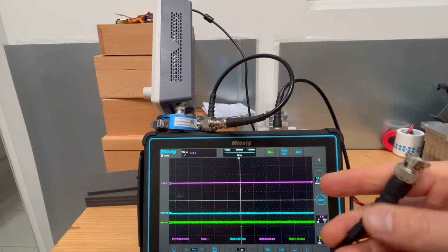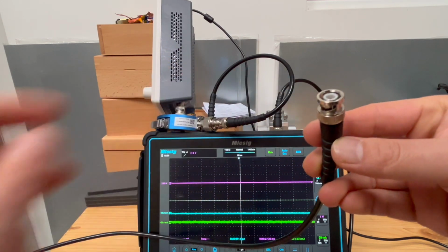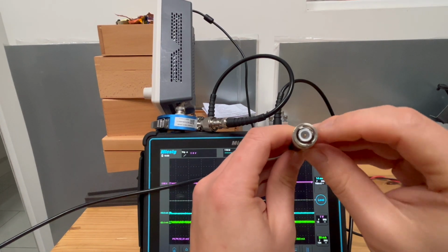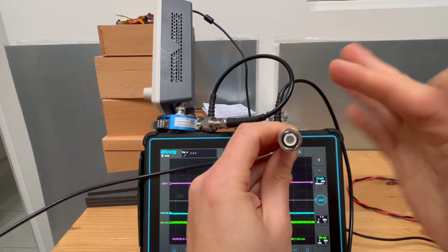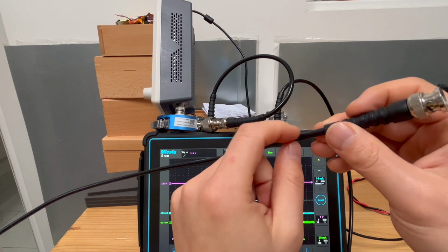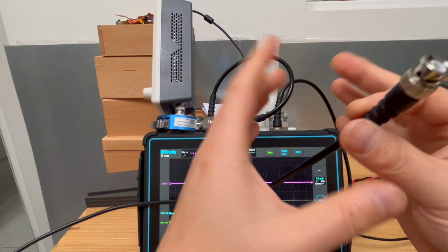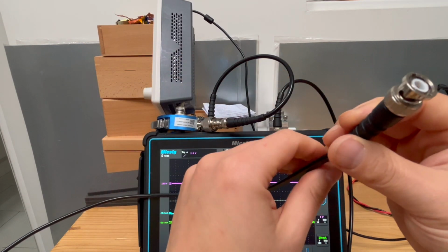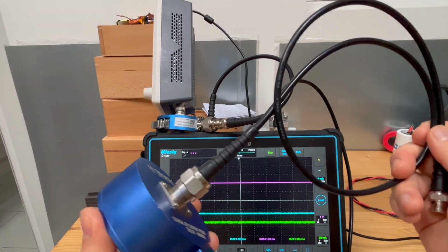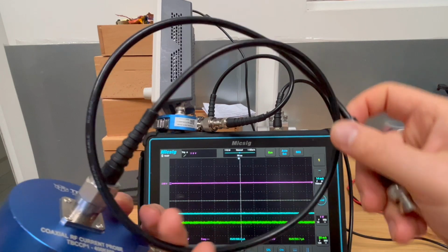But here's the challenge. How do we measure the current that's going through the shield? In fact, as RF current frequency increases, most of the return current would use the inner shield because of the skin effect. So we need to find a way of measuring the current inside the shield, because if you clamp a current clamp on the outside, according to Ampere's law or Maxwell's equations, you will end up with zero current because all the field is contained inside the shielded cable. Just to clarify, I'm not measuring the return current in this case, so let's hook it up to the oscilloscope.